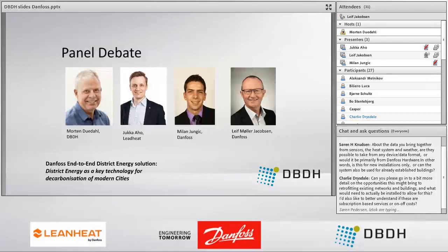So old and new, and you can also say, when we do the contingency planning, for example, maintenance, network renewing and so on, of course we have old, when we import data, we can see how old the pipes are, which type of pipes, how the insulation is and so on. And we can also look at the demand and say, okay, we have these diameters in the ground now, but once you go and change it, because you can make a hydraulic analysis, it should be replaced with another dimension, for example. So retrofitting, going from the old to the new, can be a long process, you don't change a pipe from one day to the other. It's maybe 10, 15 years. But retrofitting could also mean that you have an old network registration which is not updated. I don't know if I answer exactly what you're asking about.